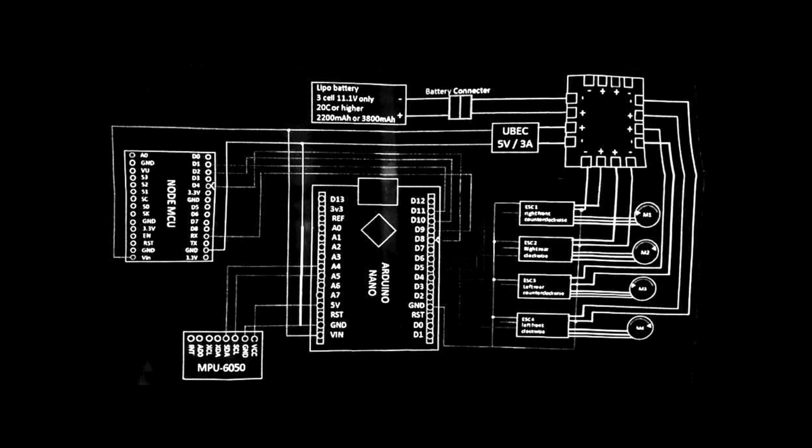The Node MCU boots up and connects the Remote XY app on the phone to receive input from the joysticks. This input is translated to the Arduino using channels. The Arduino also interacts with the MPU 6050 to understand the current configuration of the drone. It then processes these inputs and makes the required adjustments using the PID algorithm. It provides output to the ESC, which controls the power delivered to the motors and the direction of rotation, which is explained in the section on the dynamics of the drone.